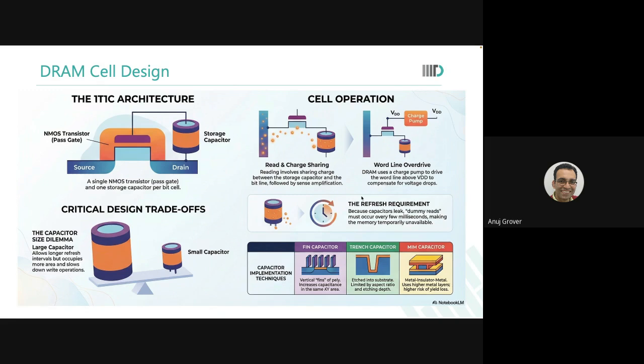However, in the DRAM, the memory cell is only one transistor and one capacitor. And when that happens, after some time, when a lot of leakage has happened, whatever you have stored inside the DRAM may evaporate. I'm using the term evaporate because we are talking about volatile memories. Volatility is something that will vanish, but that will evaporate after some time. So leakage is the cause of evaporation in DRAMs.